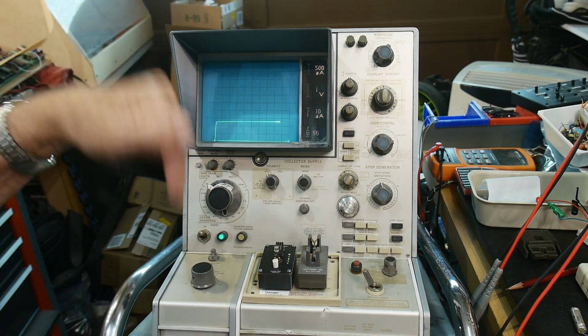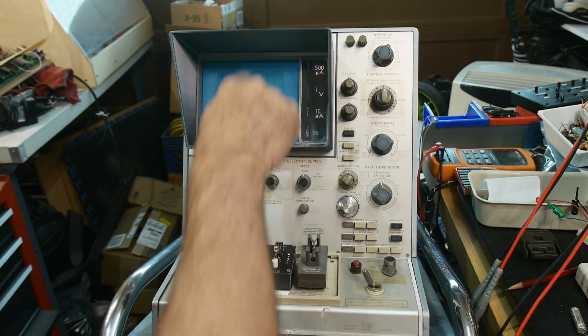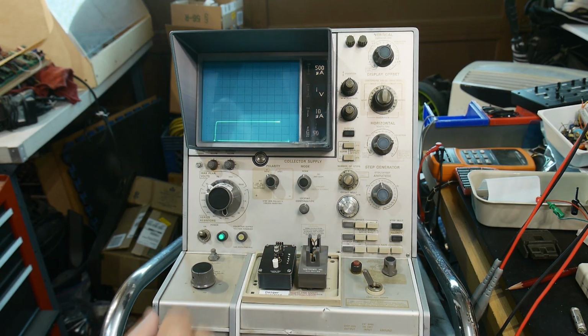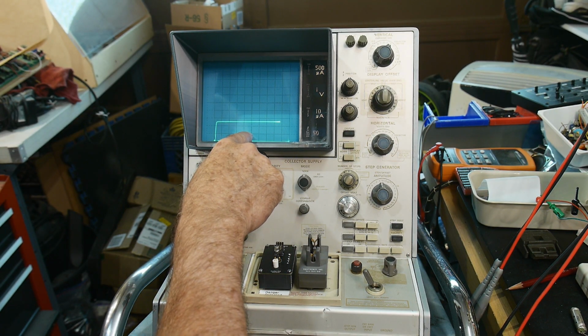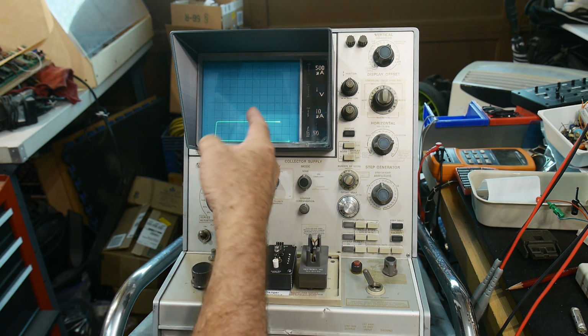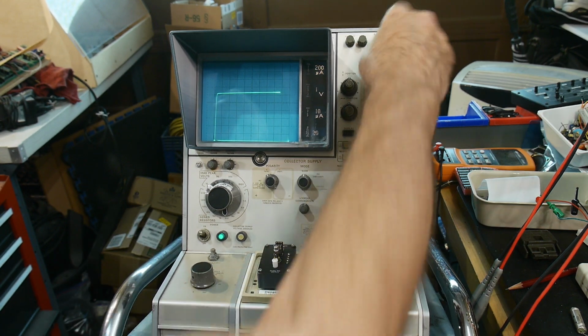And then we're going to measure the current through the transistor. Current, remember, is the y-axis. So how much current do we have? Well, we have 500 microamps per division. So we have 1 milliamp. We have about, let's see, we can make it bigger, make it easier to read. Okay, so 200.